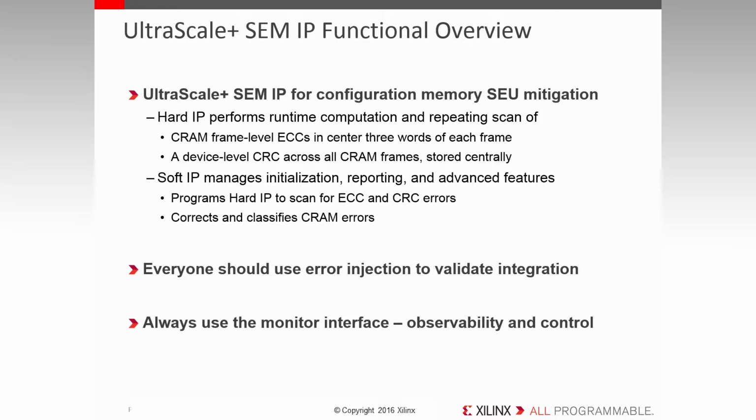In addition to runtime protection, it also provides error injection capability and diagnostic commands. These are crucial capabilities everyone should use for integration testing. If you're designing for reliability, don't you agree you should test the system response to exceptional conditions? The challenge with integration testing of this nature is creating realistic stimuli, and the UltraScale+ SEM IP delivers.